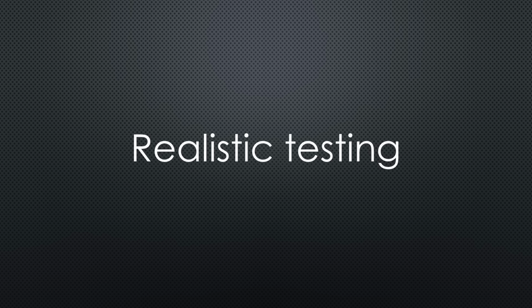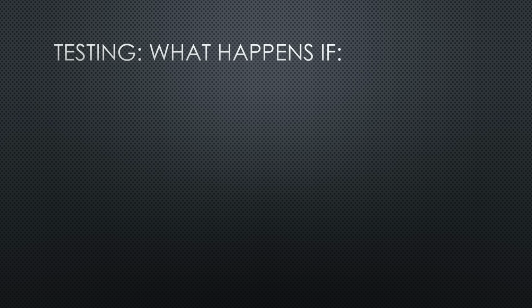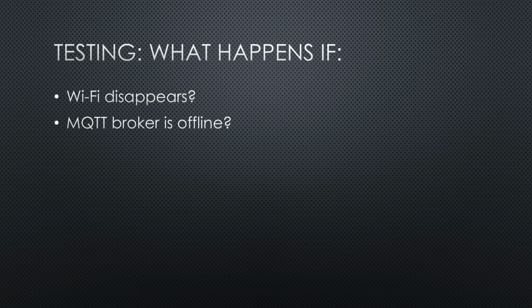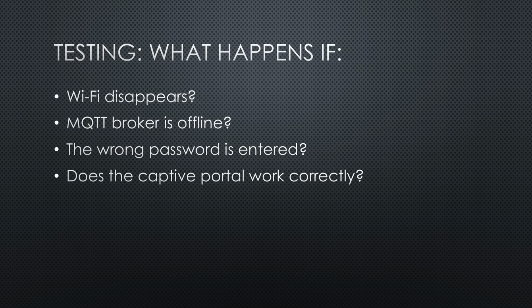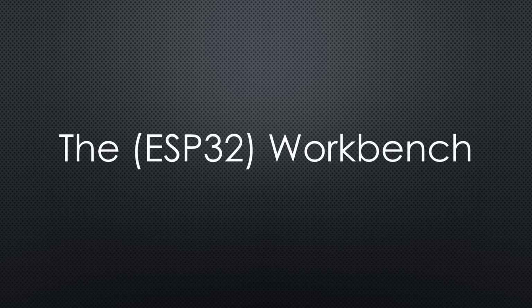Problem number two, realistic testing. Most ESP32 projects use Wi-Fi, sometimes BLE, and often MQTT. During development, I want to test situations like what happens if Wi-Fi disappears, what happens if the MQTT broker is offline, what happens if the wrong password is entered, does the captive portal work correctly, and so on. But I cannot simply turn off my home Wi-Fi or my production MQTT broker just to run tests. So I built something I called ESP32 workbench.